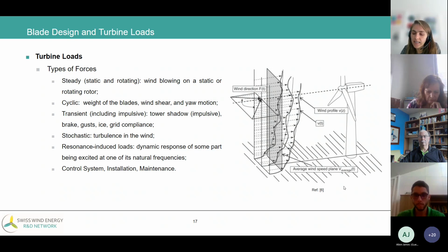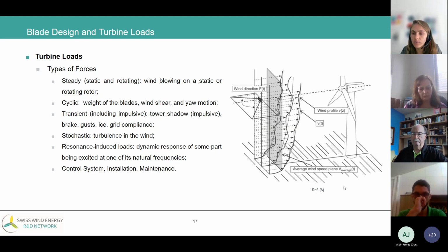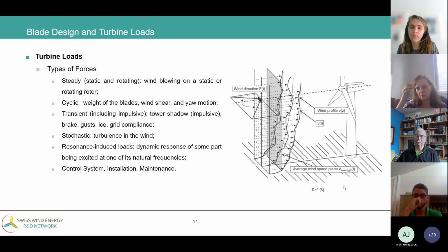Yeah, sure. I think we are aligned here on the comment. You weigh your blade once you leave the factory. You then install it, and then you have ways to do some tests on the turbine to see if the estimation of the frequency is right. Of course, you expect not to be wrong, but you measure this blade frequency once you install the blade. You have ways to measure this.